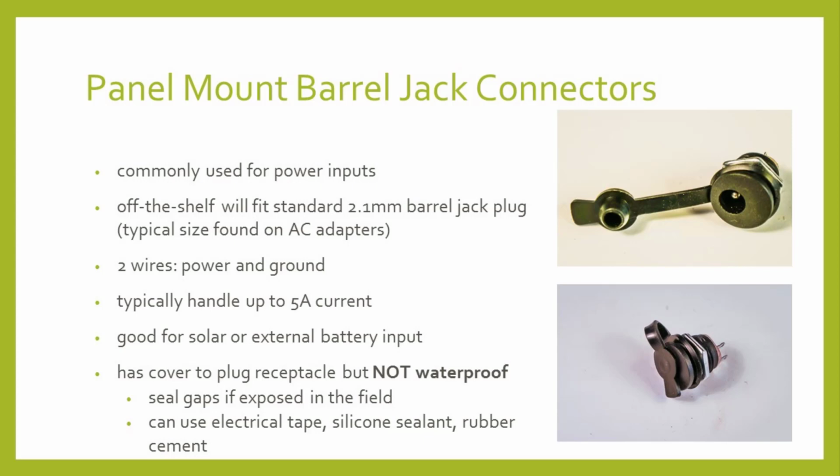These connectors aren't waterproof, however, so if you'll be using them in an exposed setting, you'll need to use secondary protection to prevent moisture. This could be electrical tape, silicone sealant, rubber cement, etc.